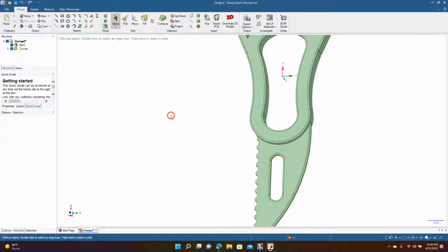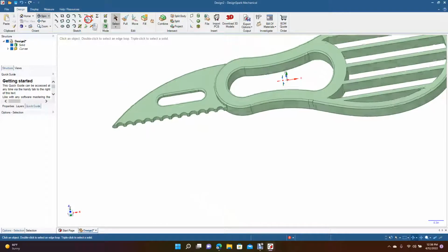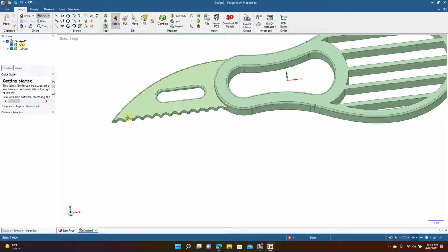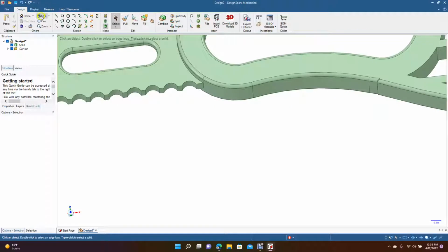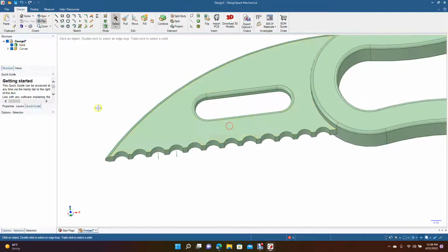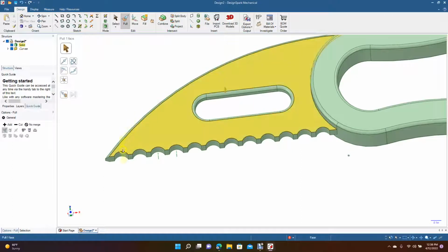All right, not too bad. Doesn't look too bad. Go ahead and spin this. The only thing I wanted to do is add a little bit of depth to the blade. So we'll go ahead and Control plus to zoom in. And we'll just see what we can get away with here. Chamfer. I guess 0.02 is going to be about it. So 0.02, 0.02, and just kind of continue that all the way down.